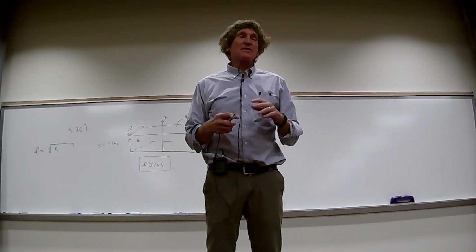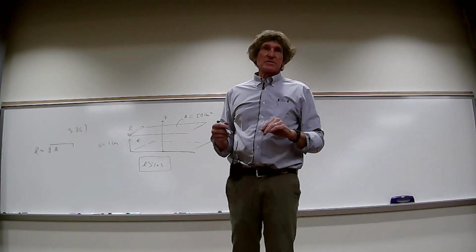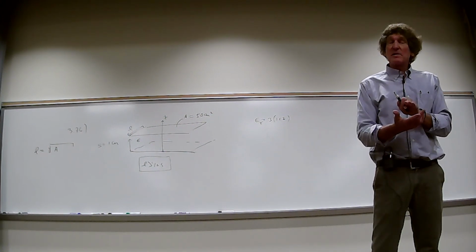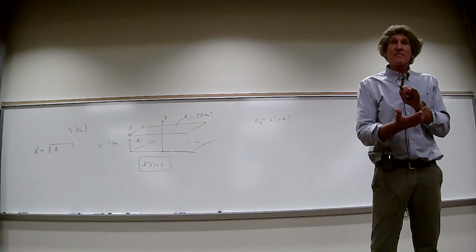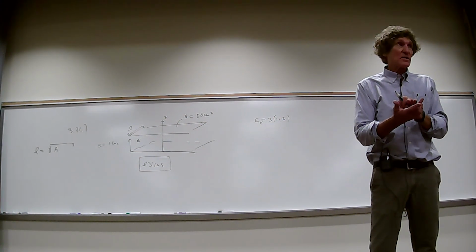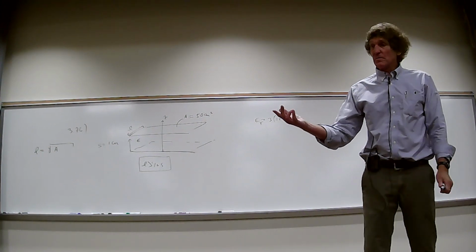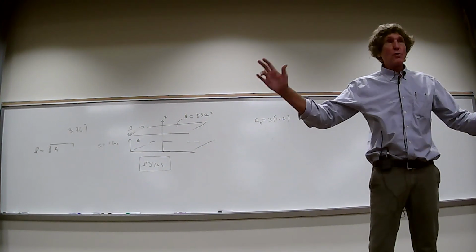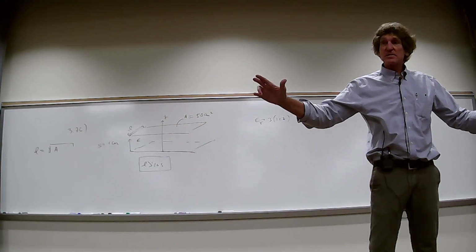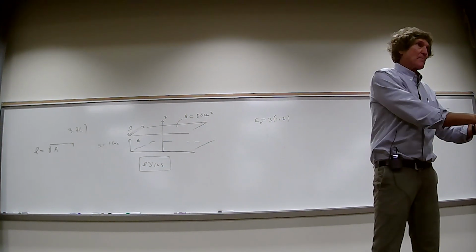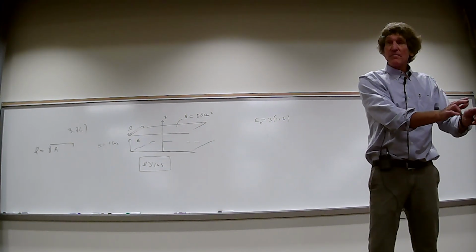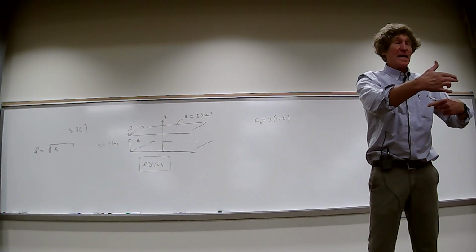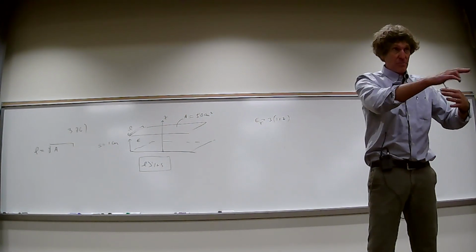Here's the classic thing. Now, I guess they don't do it. Usually capacitors, a lot of them back in the day when they were trying to make them cheap, are made with two plates, but it doesn't matter about the geometry. They just have to be separated by that dielectric and have a constant spacing, all right? So what they do is take aluminum foil, maybe a couple meters long, put it down, and then put wax paper on top of that. Then they take some aluminum foil that'll be slightly thinner, so that the wax paper will insulate the inner from the outer one, and put it on there.